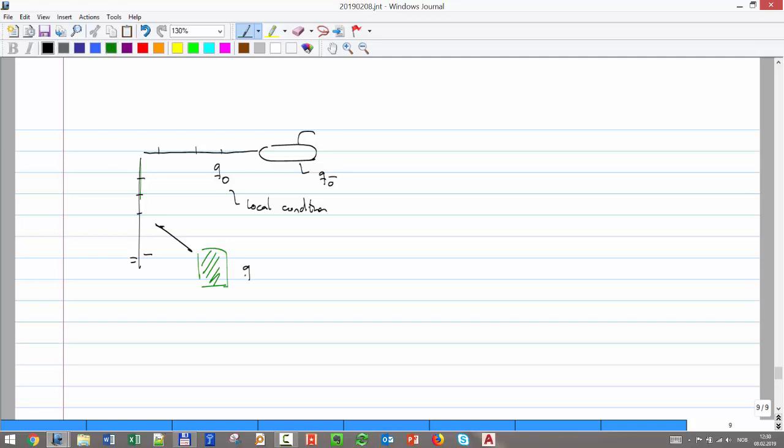So this QO will actually be bigger than QO at standard conditions. Let's say that this is 10,000 barrels, and this one might be 12,000. Now, when you go to another place here, maybe some of the gas came out of solution, and you have oil. In this case, the Q oil is maybe still going to be bigger, but I don't know. Here we said 12,000, and here it might be 11,000, because of the gas that you're losing.